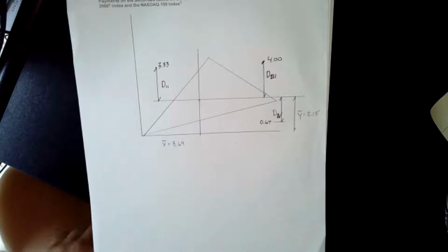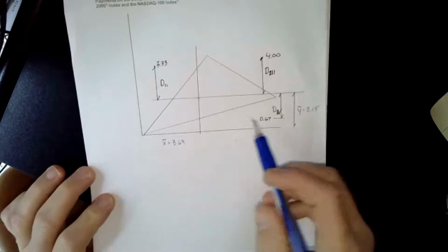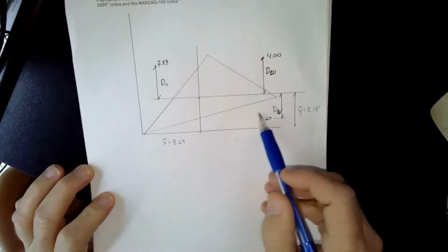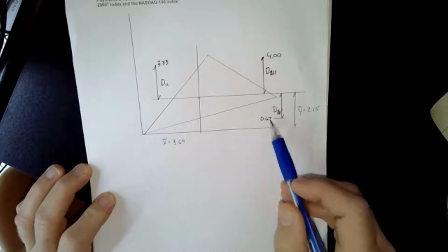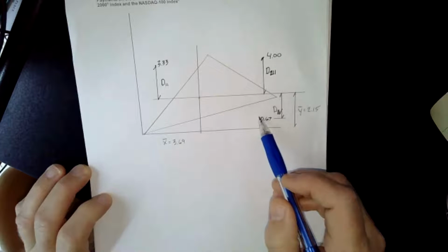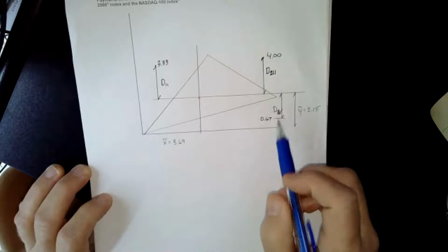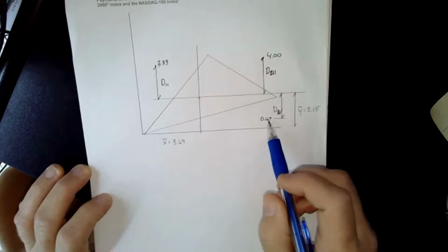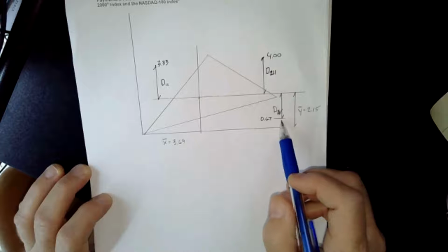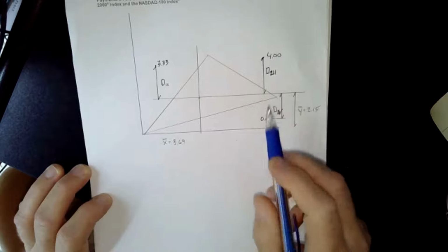So when you're doing the parallel axis theorem, of course, we know that we want to take each piece. So for example, if we had this triangle, we would say, okay, what's the moment of inertia of a triangle? Well, about its centroid, it's 1/36 b h cubed. And that of course depends on the orientation.